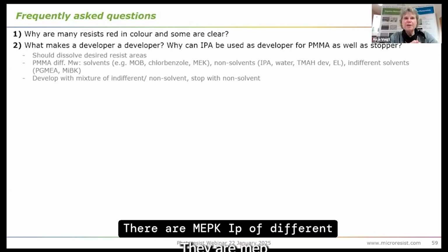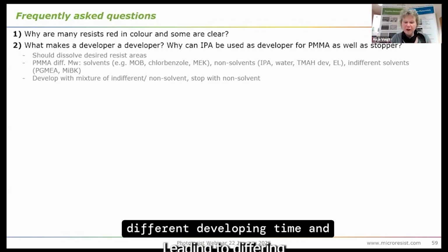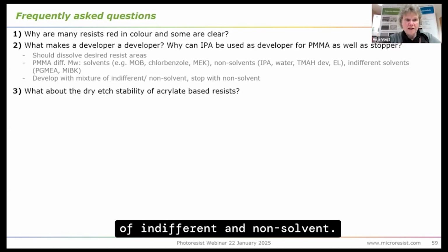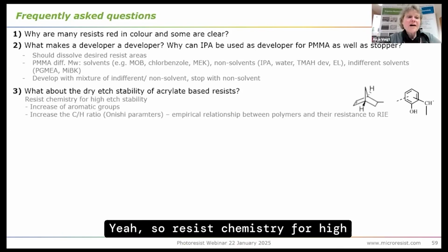There are MIBK IPA mixtures of different ratios available, leading to different developing time and throughput. So that's a clearly defined ratio of indifferent and non-solvent.